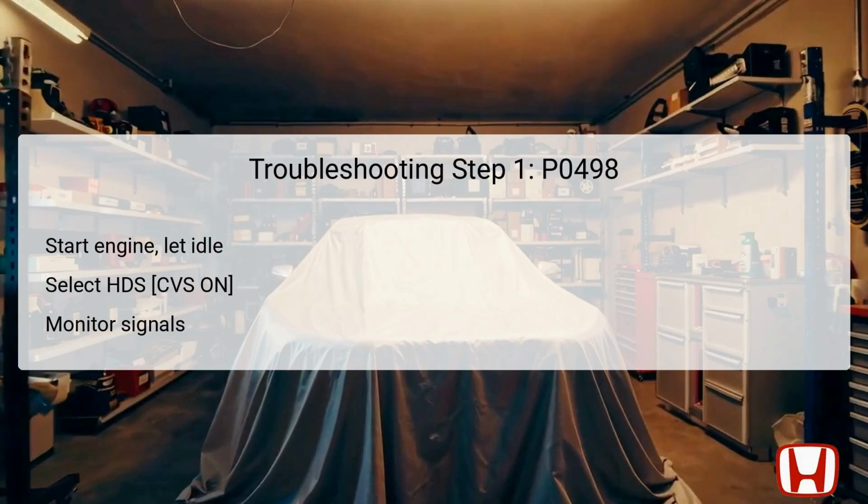Monitoring the outputs from the PCM at this stage will provide insight into whether the system functions correctly or if it still registers a fault indicative of the trouble code. Document any irregularities, as they will guide further inspection steps.